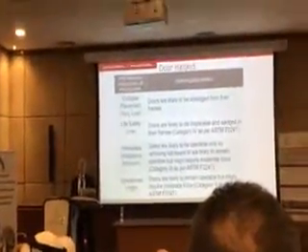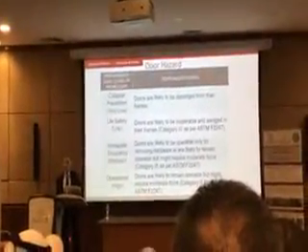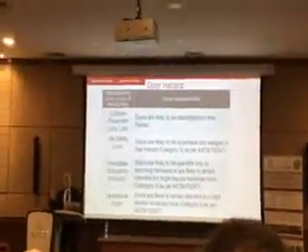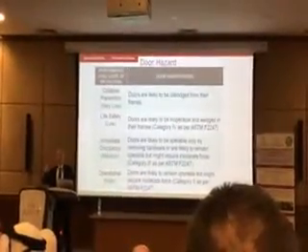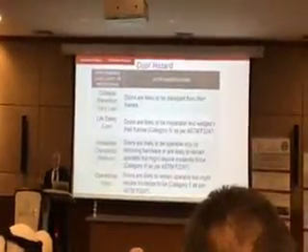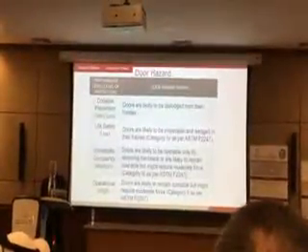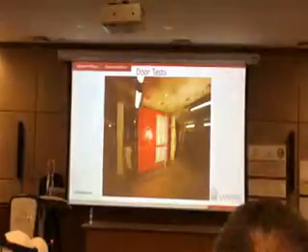And similarly, doors have different standards and different performance levels. For example, if it's a high level of protection door, it has to be operable after the event. After the blast, you should be able to open the door and leave. But if it's a low level of protection, so long as you can push it open, the mechanism need not work. So there are different levels specified in ASTM F2247. There's another standard.